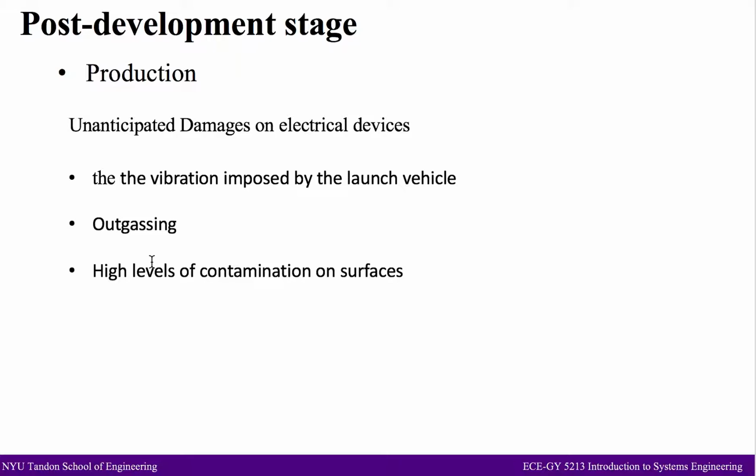Pyrotechnic shock is the dynamic structural shock that occurs when an explosion happens on a structure. So the pyroshock is the response of the structure to a high frequency, high magnitude stress wave that travels through the structure as a result of an explosive charge, like the ones used in a satellite injection or the separation of two stages of a multi-stage rocket.